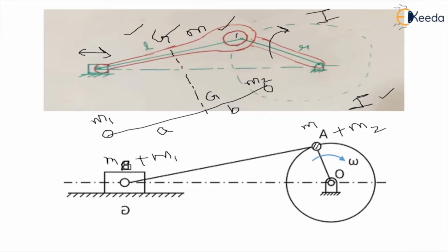So the masses at the crank pin and the gudgeon pin increase because we are converting the connecting rod into a system having 2 point masses at the ends joined by a massless link.